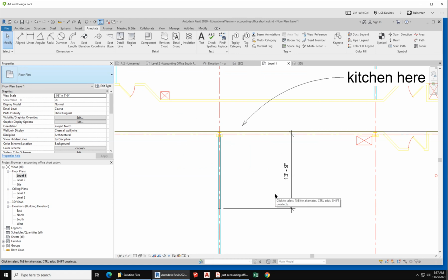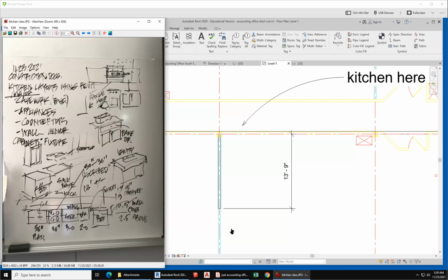Let me load the drawing that I put on the board in class the other day. I'm going to pause this recording. Okay. So the kitchen we want to draw into that 14 feet more or less, from left to right, is apparent here. Let me circle it with a rectangle. This is what I'm drawing, right? There's a plan drawing. So I'm starting from my left, 36-inch base, 30-inch range, 3-foot sink base.